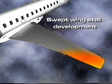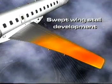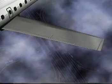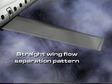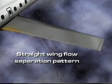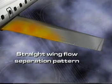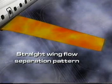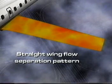If an actual wing were allowed to stall in this fashion, aileron buffet would occur, and the wing would drop. No nose-down moment and very little aileron effectiveness would be felt. When sweep back and taper is combined in a wing, the tip stall tendency is further aggravated. The straight wing exhibits low lift at the tip and high lift at the root, which contributes a lot for favorable stall pattern characteristics, adequately signaled by the stall warning buffet, adequate aileron effectiveness, and the usual strong nose-down moment.